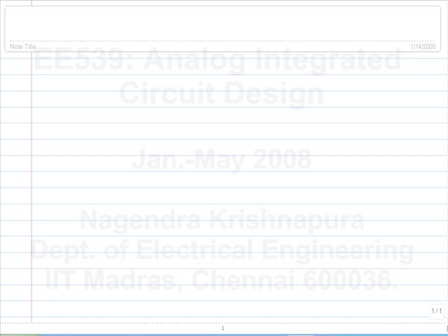The other day we were discussing how you can make feedback systems with op-amps. At the same time, to make the op-amp behave like an integrator, it has to be biased in the correct region. So whatever feedback network you have to do your signal processing function must also provide DC negative feedback around the op-amp. Okay?